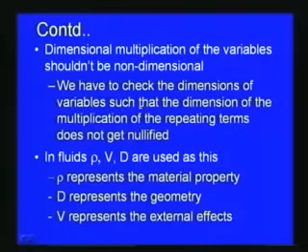So we have to check the dimensions of variables such that the dimension of the multiplication of the repeating terms does not get nullified. So this is another important point. The dimensional multiplication of the variables should not be non-dimensional.